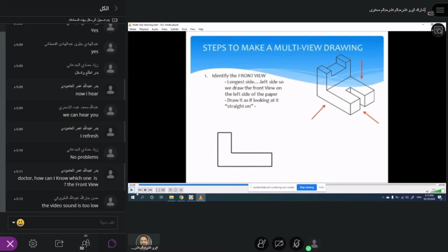Also, when you see the isometric view, you see the sides which are actually inclined when you see from the horizontal axis, correct? If you draw a horizontal axis, this object is actually inclined. But when you draw the front view, I mean the multi view, you take this side and keep your LOS, the line of sight, parallel to the edges, right? So you just watch it, line of sight is parallel to the edges, so that you will end up with a front view like this. Okay, that's another convention you should keep in mind.